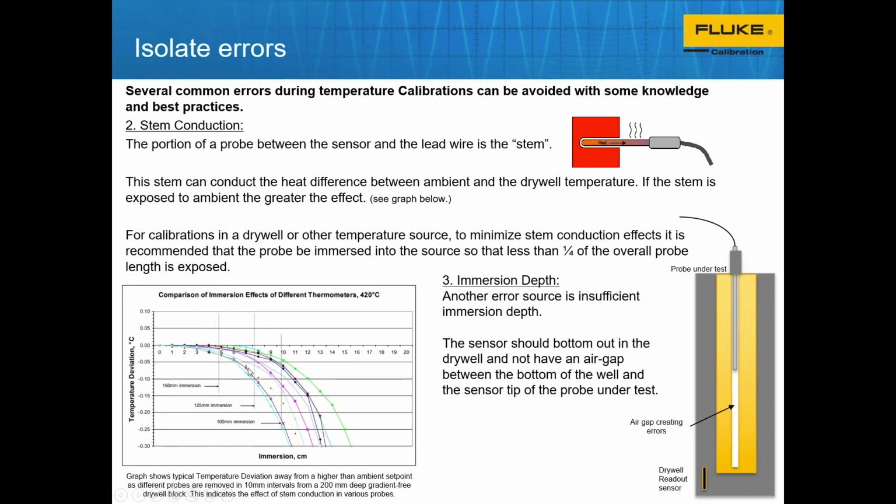People don't recognize this. They probably don't know that it's happening, but if I take that RTD probe example with that temp stick, on paper it has beautiful accuracies, but when I put a big long stem conduction on it, I'm in many cases not eliminating, but significantly reducing my accuracies relative to the standard that's written on the data sheet.